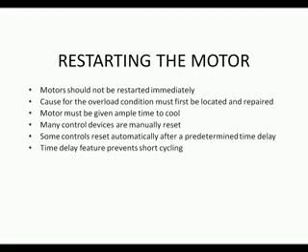This is an example of a magnetic overload device. Notice the large winding there in the center. It captures the high amperages, but does not have much of a voltage drop, so it can be wired in series with the motor.